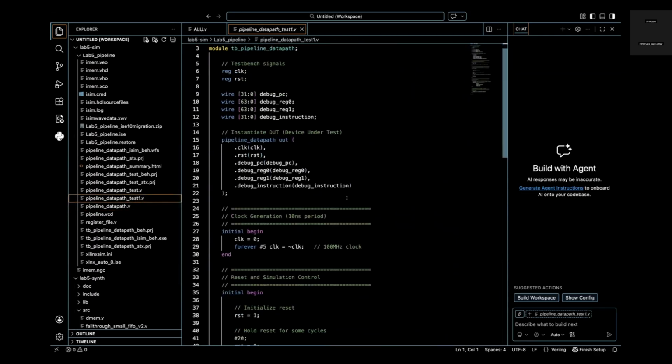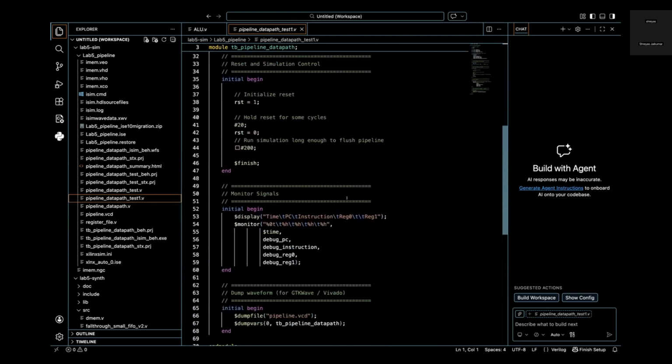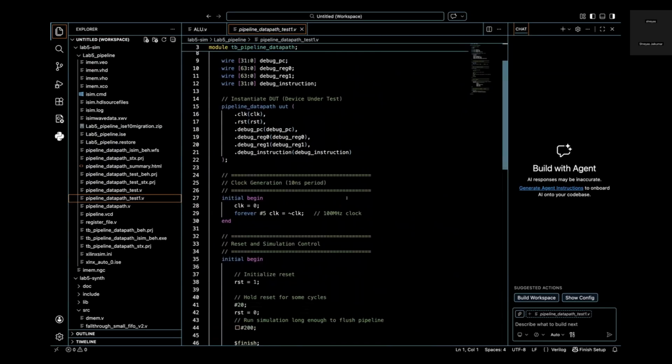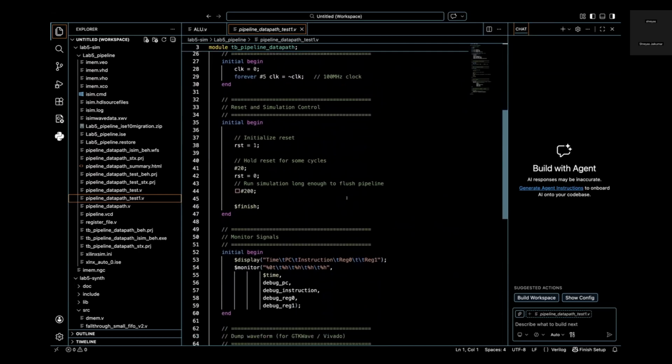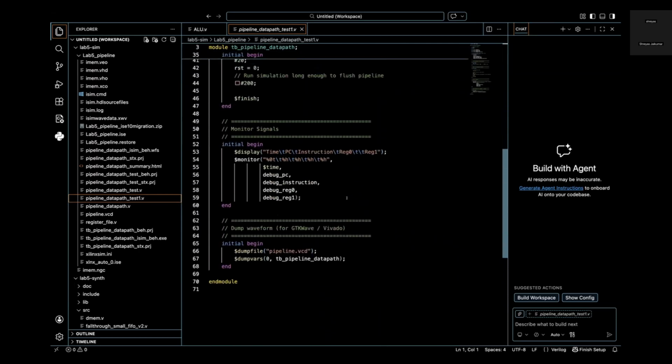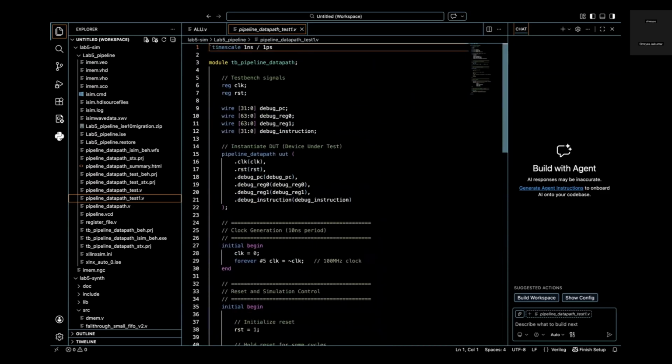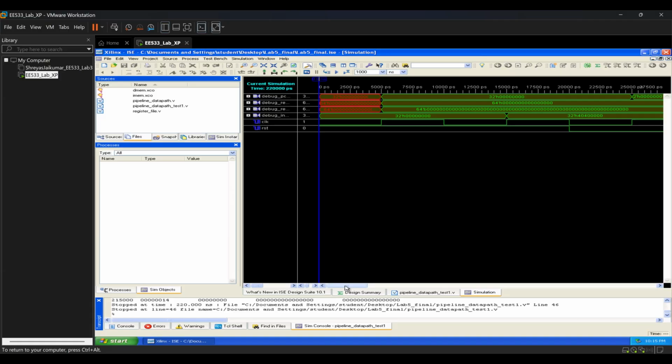So this is basically a small test bench code that we wrote. And now in a minute, I'm going to shift to my other computer and show the simulated results. The instruction memory that we preloaded is exactly based on what is specified in the PDF manual. So it's a total of 6 clocks. So the end visibility will happen in the 7th clock cycle, end of 6th, beginning of 7th.